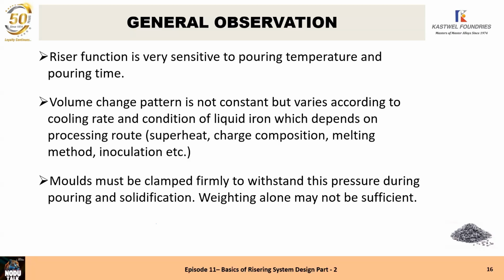Process control. Molds must be clamped firmly to withstand this pressure during pouring and solidification. Weighting or putting counterweights alone may not be sufficient. So just by putting counterweights, one may not be able to withstand the extremely high pressure on the mold, which is generated when the solidification starts in the mold cavity with the metal.